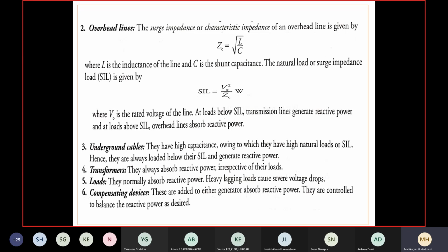Along with that, the system to which the power is being transferred over the transmission line possesses high inductiveness or high capacitiveness depending upon the situation. In a highly loaded, ill-conditioned power system, we suffer from a sluggish and lagging power factor. Then the overhead line, being highly inductive, suffers from absorption. They absorb reactive power because they are highly inductive in nature. They keep absorbing reactive power.